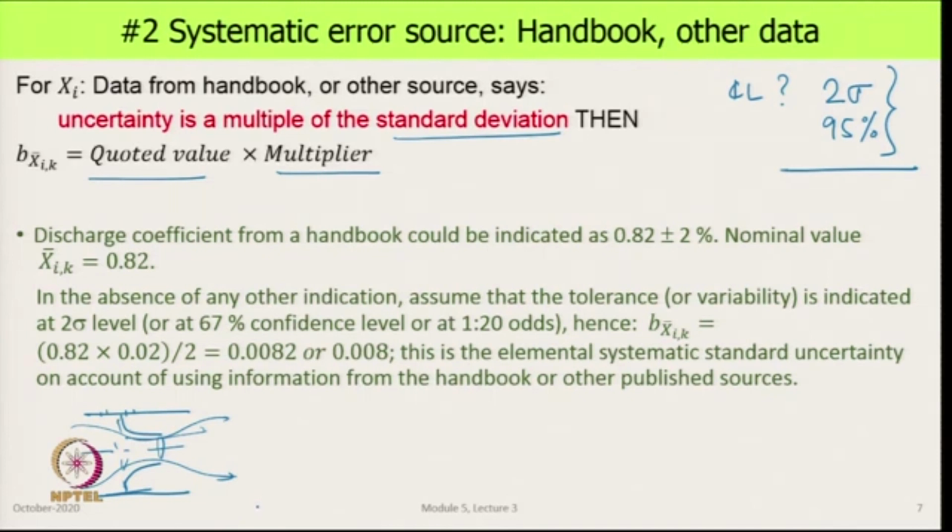From that pressure we calculate, using a formula, the flow rate, and that calculation is off from the real value by a constant which is called the discharge coefficient. So, we multiply that calculation by CD and we get the actual value of the flow rate.